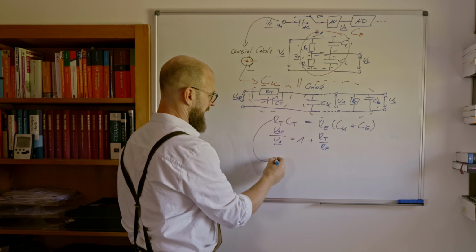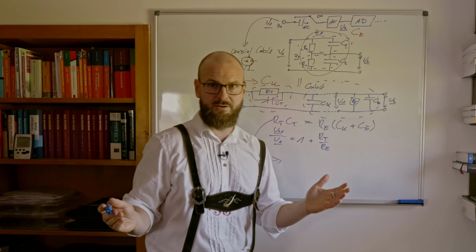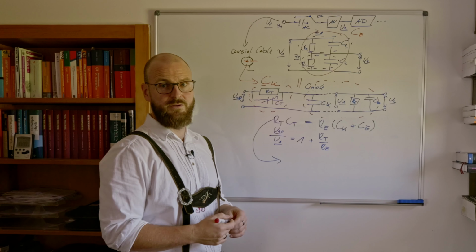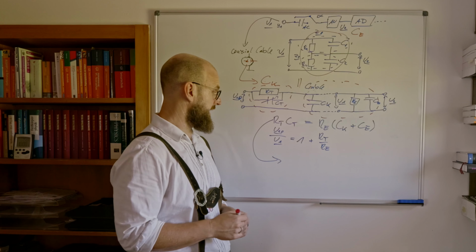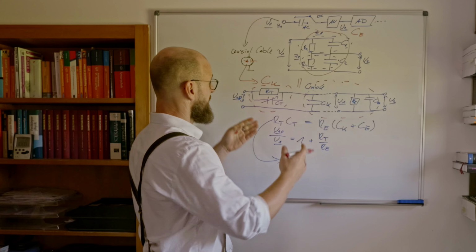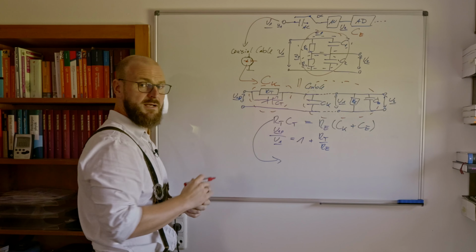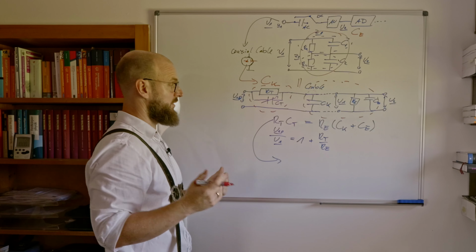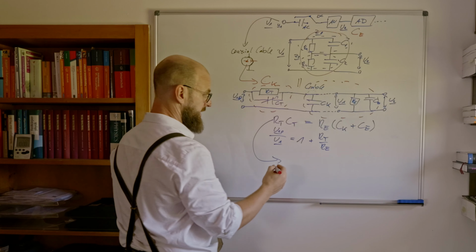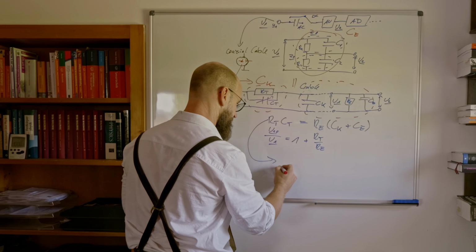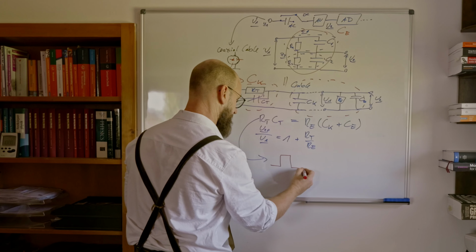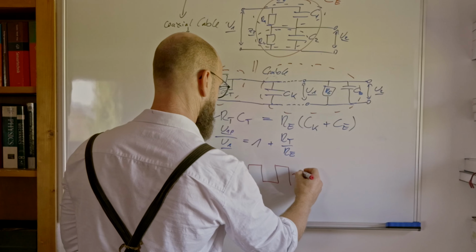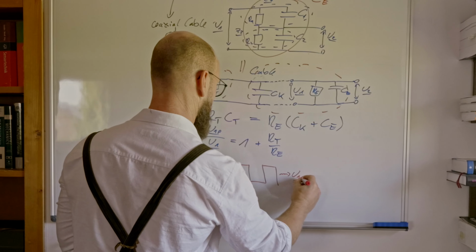Now the question is, how to adapt that? Yes, you can calculate along, but doing the practical stuff, you won't be able to do a lot of adaptions. So what you normally do to adjust the capacitance of your probe is you apply a known rectangular voltage signal to your input of your probe.